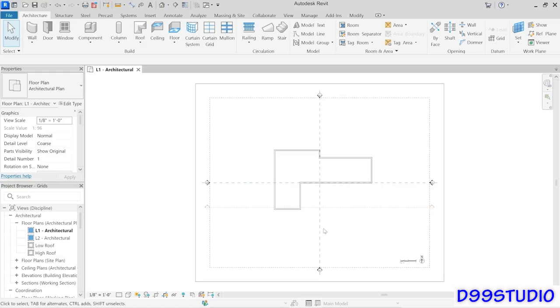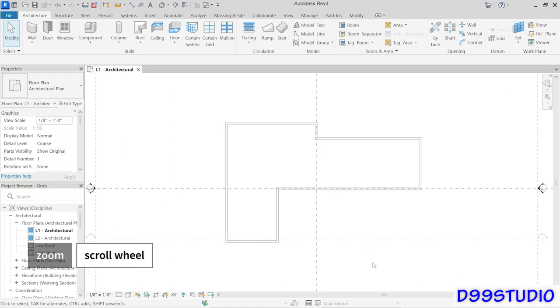Now, I'm going to work here in this floor plan, and to help us get started, I've created some basic walls here to kind of represent the footprint of the building that we're after. Now, I did this just for convenience. It's not required that you have walls to start before you create the grids, but I just thought it would give us a little bit more focus while we're working here. So I do recommend that you continue in my exercise file rather than trying to use your own version for that reason. Now, I'm going to zoom in just a little bit here so that we can get a better look at that building area. And then let's go ahead and get started creating our grids.